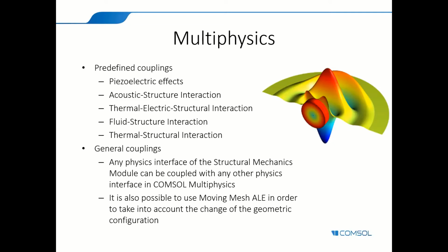You also have acoustic-structure interaction, thermoelectric effect, or thermoelectric structure interaction. One of the very interesting features we have is the fluid-structure interaction. You can simulate how a fluid interacts with a solid body, either one-way coupled or two-way coupled between the fluid and the solid. So we have the FSI, or fluid-structure interaction. We also have the thermal-structure interaction, which is one step less than the thermoelectric structure interaction, so you're combining just the heat transfer part with the structural mechanics. You can see how heating or cooling a body affects the stresses inside the body, as we're going to see in one of the examples we're going to do today.